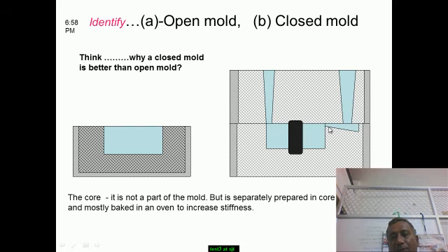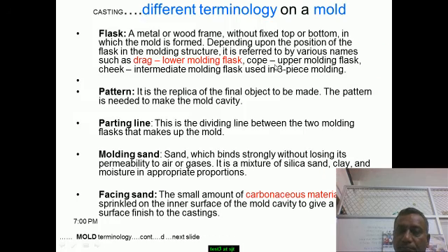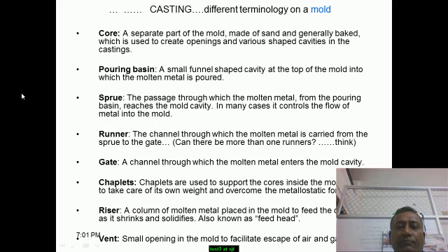At the end of this runner and at the beginning of the cavity, we have named it the gate, through which the molten metal glides down. Repeat, it is not poured down, it glides down all the way and just fills it up. Then, after filling it up, the red hot molten metal rises up here. The pouring man will get the indication.